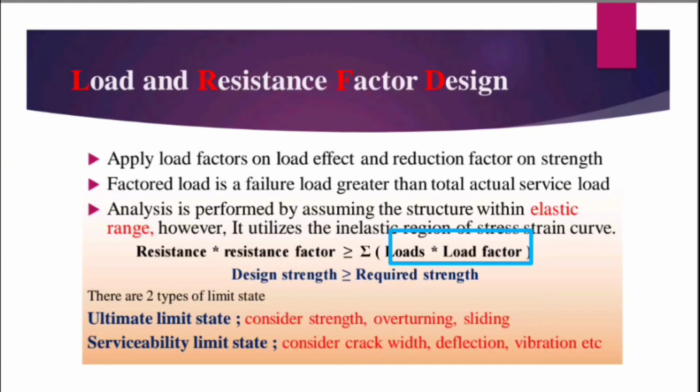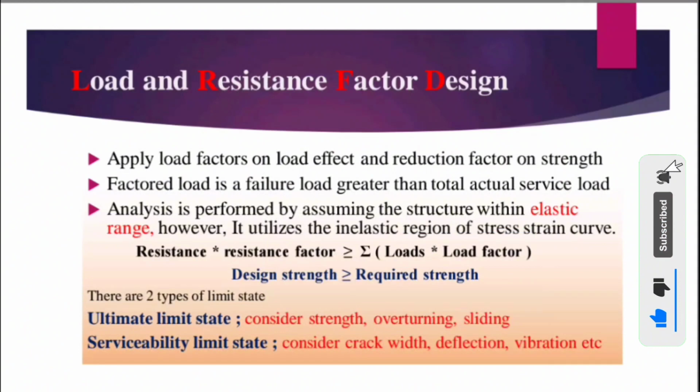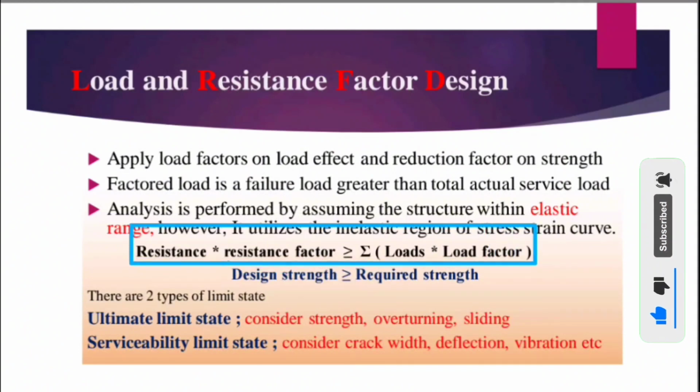In the next slide we will see the different load combinations, that when only the dead load occurs, what will be the load factor. So this is the main design equation, that the design strength should be greater than or equal to the required strength. Every design philosophy covers this equation.